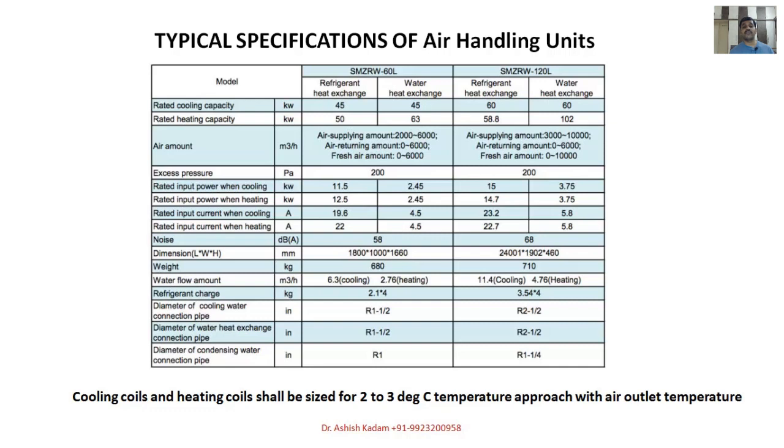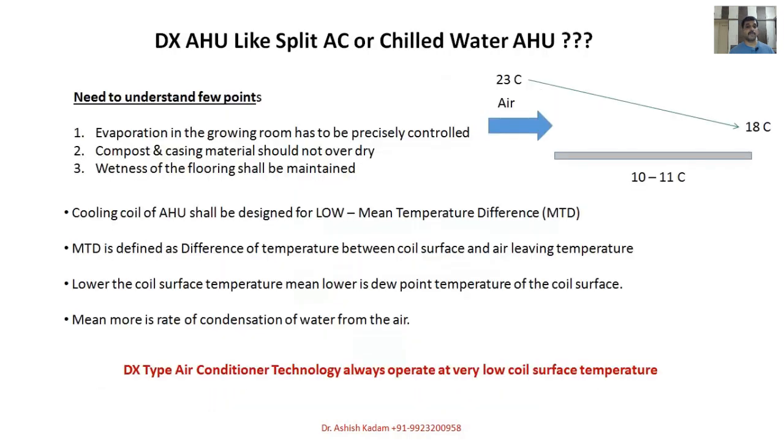And if you go for frequent watering, it will create a problem for the caps of the mushroom. So we have to design these cooling coils and heating coils for the right temperature approach. Of course your investment will be a little bit more if you go for small temperature differences between the water and the air outlet temperature. So this is the point we are discussing here.